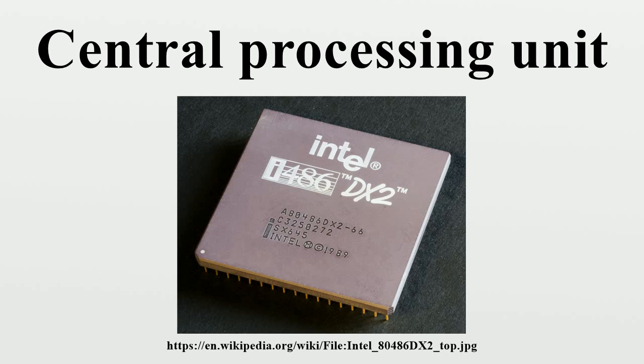Almost all common CPUs today can be very accurately described as von Neumann stored program machines. As the aforementioned Moore's law continues to hold true, concerns have arisen about the limits of integrated circuit transistor technology. Extreme miniaturization of electronic gates is causing the effects of phenomena like electromigration and sub-threshold leakage to become much more significant.